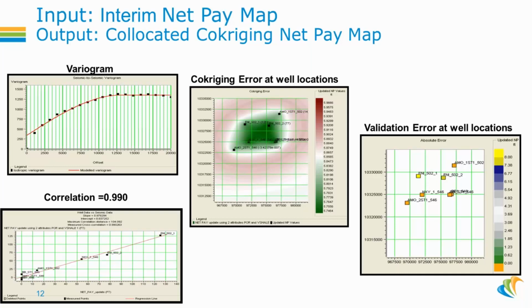To improve upon this map, I'm going to run a geostatistical interpolation technique called collocated co-kriging. MapPredict contains a range of geostatistical display and analysis tools such as cross-plotting, histogram, variogram analysis, well-to-well variograms, well-to-seismic variograms, and it also has standard mapping interpolation techniques incorporated, such as kriging, co-kriging, and conditional simulation techniques.